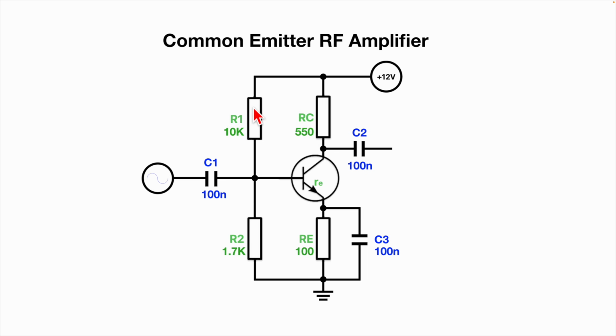I wanted to make it as bulletproof as possible to any changes in the DC beta of individual transistors. And I say that advisedly because that's the point of this. It's because different transistors have different values of DC beta, and you don't want to plug a different one in and get completely different results.